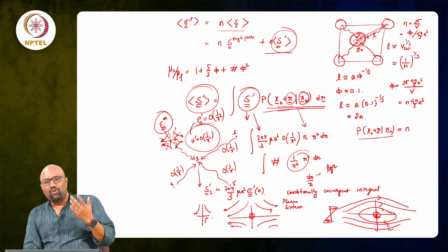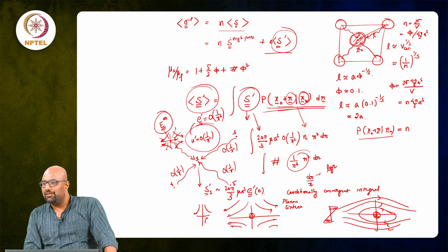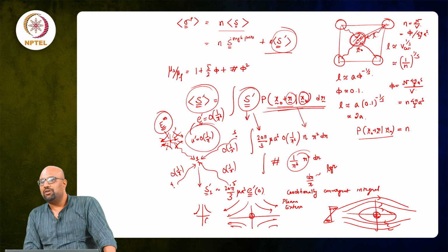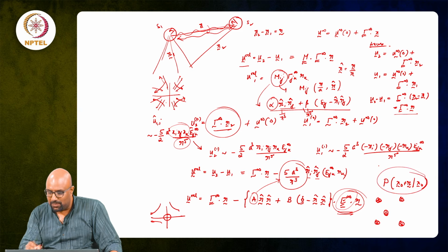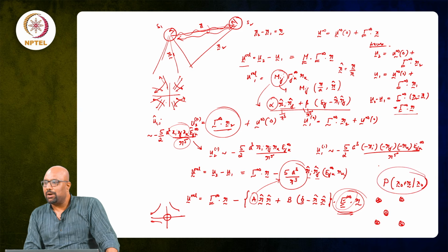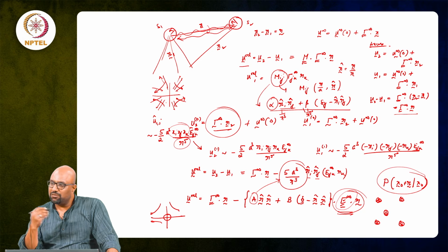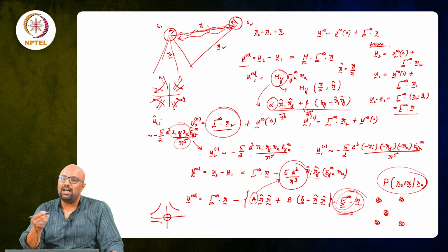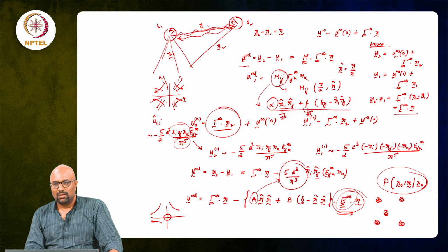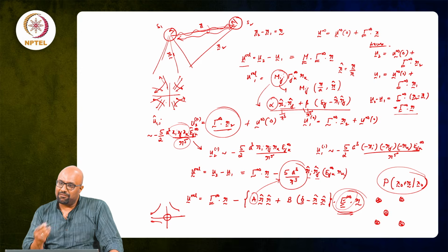So, for every flow there will be different kinds of trajectories of your neighbors with respect to your position, which means that when you are trying to calculate this pair probability, it is a function of your relative velocity. So, you need to find that pair probability when you are doing a particular kind of flow. So, this makes the effort more challenging.